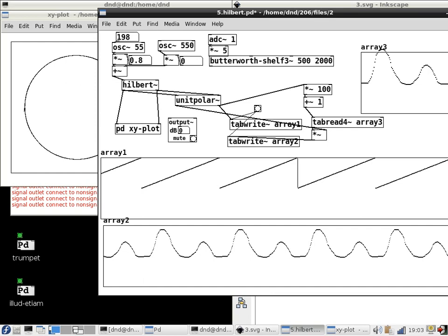Right. Okay, so now what I have is an amplitude preserving wave shaping function which will at least take an incoming sinusoid and turn it into any waveform that I want with an amplitude that varies proportionally to the amplitude of the incoming sinusoid. So now you get out your trumpet and get a microphone and blow it into this thing, and your trumpet is playing any waveform that you want. Except a couple of things. One is everyone's going to hear the trumpet. So I'm not sure in the case of a trumpet this is actually going to be a useful wave shaping technique. I use it with a guitar, and it works just great because you can make a guitar not make any sound at all.